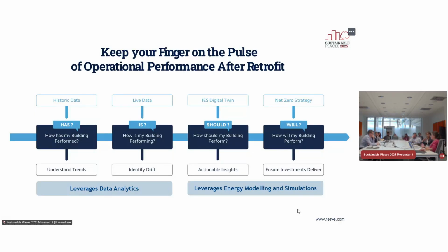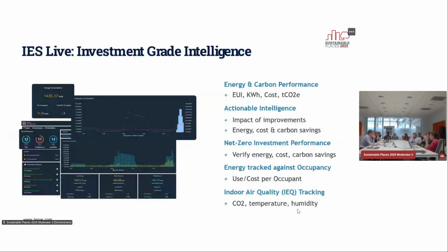And the most recent tool that we launched in this is IES Live. It's an online data platform, and it brings together the live data from the site, the digital twin and simulated data from the model. And so basically, it uses the digital model over the whole life cycle, right? It supports that ongoing optimization of energy and costs. Like you can see how the energy is used and in that identify if there is that performance drift.